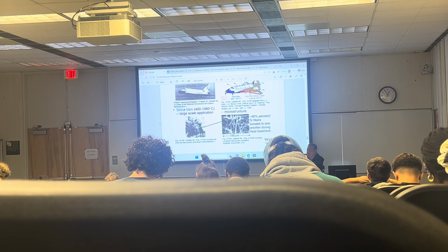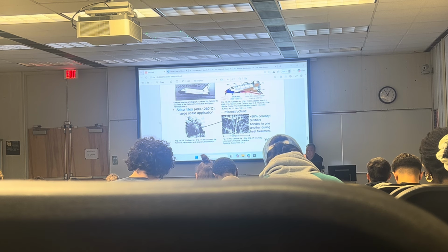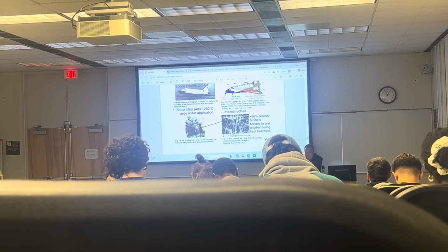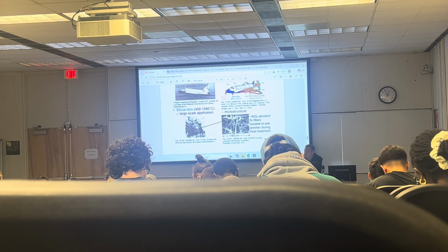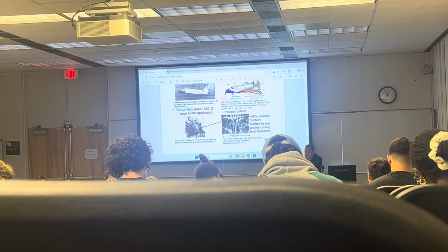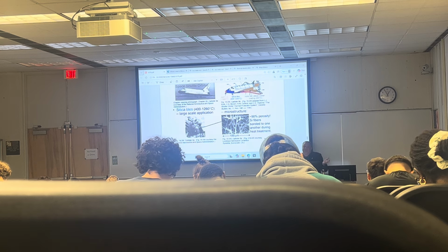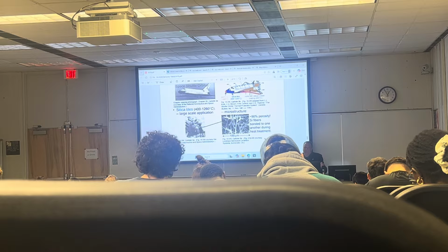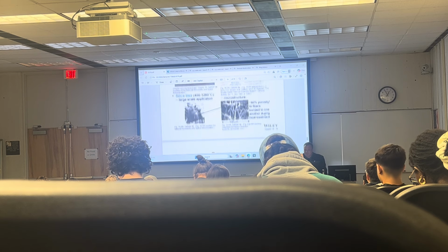So it can expand and contract if needed, and so that you can replace it. Okay? And some of them would fall off during this very violent procedure. But what it really is, is 90% porous silicon fibers. And you can see the structure. This is 100 micron. It's basically nothing. I wouldn't say it's nothing. But this system provides very good thermal insulation.